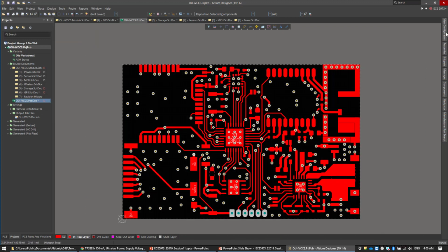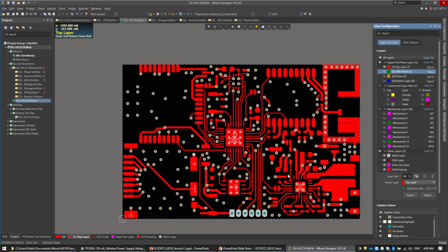Now, once you are done with routing the main component, the last thing you need to route is the power traces and the ground. This is general. Sometimes you need to route the power first, but in general, you just fan out your ground and power pins into vias, and now you have a power plane and a ground plane where everything ground and everything power will connect together.